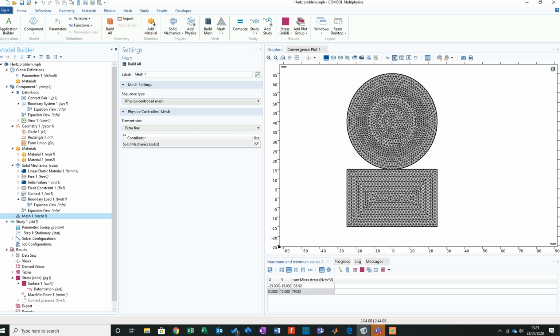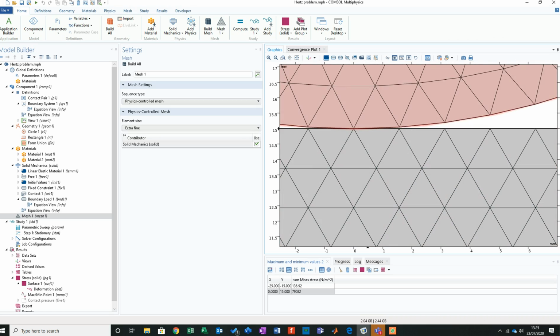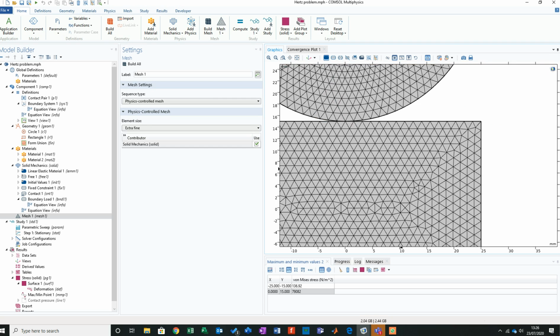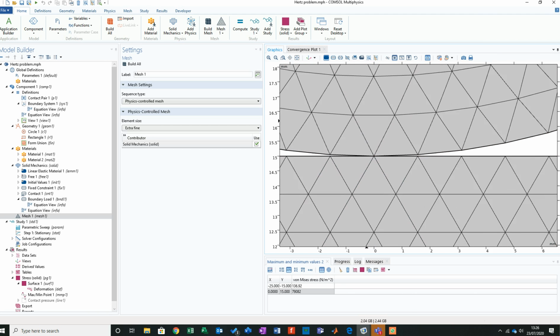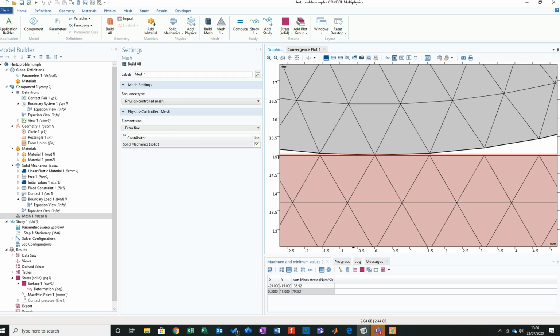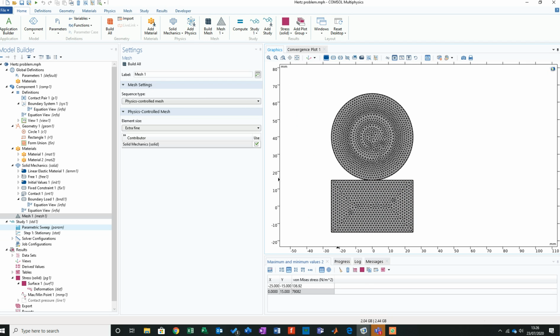Let's revisit the mesh. Now, I want to go into a bit more depth on mesh. I think the next video I'm going to do is about why we do what we do. So if I zoom in, we're talking about 1, 2, 3 nodes of contact between them. A little bit big, a little bit too much. It's distributing this across this single point here, and we've obviously got about 2 by 2 matrices for our stiffness matrix. So it's not a very accurate representation. When you look at it you go, wow, that's amazing, but it's actually not very good.